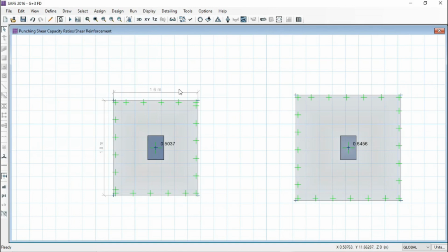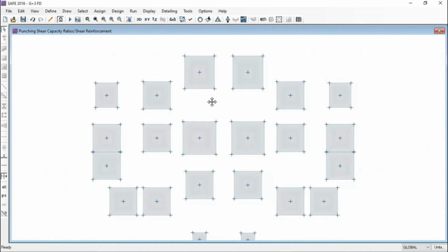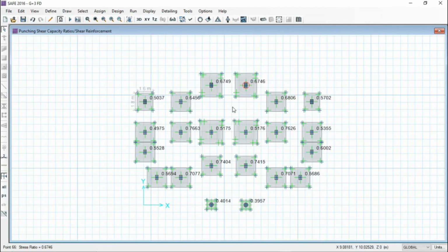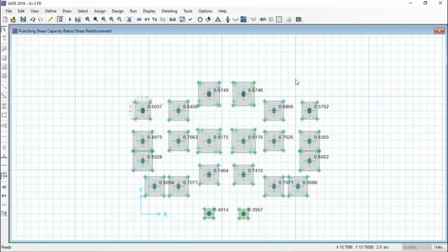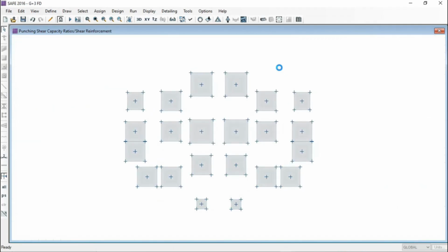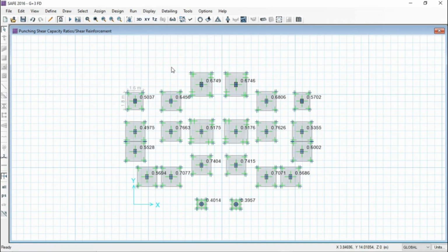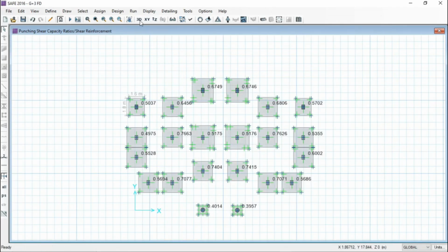So that's how you can do the design. You have to do the design cost effectively. You have to ensure that your design is cost effective, and you have to check everything. Your deflection and your SBC should be around 10% or 20% below the permissible limit. You have to check reinforcement also, that the reinforcement you are getting is about 1 to 2% in foundation. Around 1.5% is cost effective, otherwise it will be over reinforced.